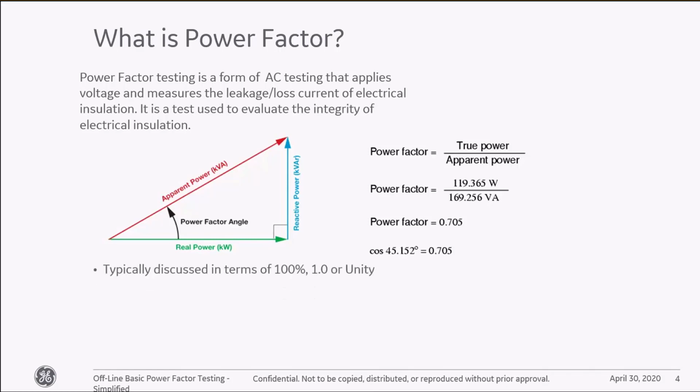Anyway, I checked it, and it was like 92%. Well, there's a guy out of Florida who years ago had put together some power factor optimization equipment, let's call it that, as a small box. I connected it up to the main bus, and every time an air conditioner came on, my power factor went back up to about 99.8. So it made my air conditioner tremendously more efficient from that standpoint, and as a result I'm not paying for power I'm not using, that I'm wasting. So the idea is to make things as optimal as possible.